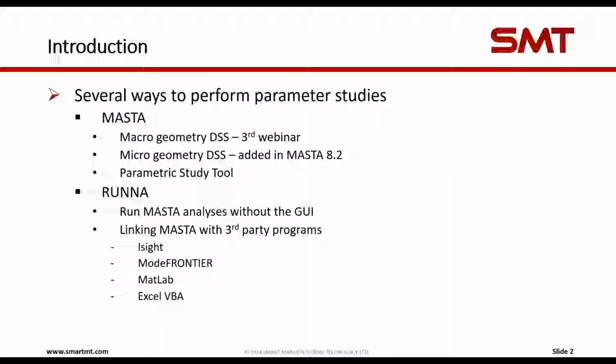We also have the Parametric Study tool, which is one of the features I'll be demonstrating today. It allows for linear sweep, Monte Carlo, and full factorial design of experiment analyses to be conducted on your designs. As opposed to the design space search features, which work on single gear sets, the Parametric Study tool works on a system level. Examples of use include manufacturing tolerance studies or bearing preload studies to find optimum preload.